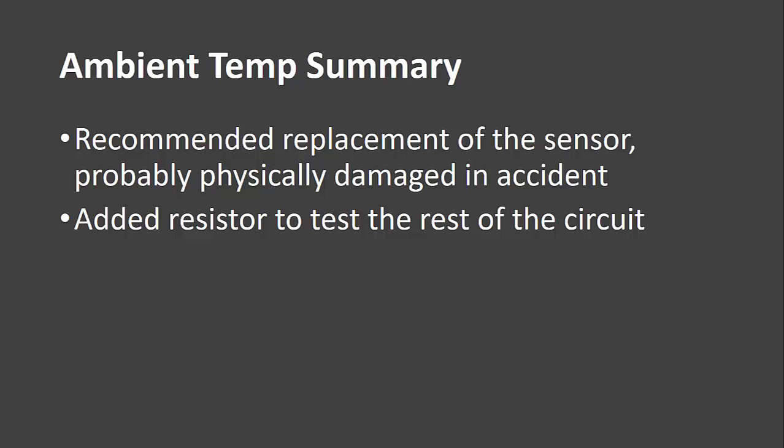So the test, there was an injector test. There is an injector test in IDS, and when you would do it, the engine had to be fully warmed up. So I would trick the temp sensor into thinking the engine's warmed up to allow that test to occur when the engine was cold.